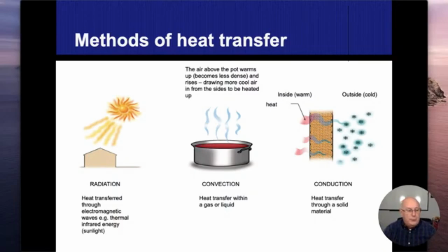Convection: anytime we move heat through water or air, we're going to be calling it convection. So in furnaces, we have ductwork. We heat up the heat exchanger, we blow our circulation air around the heat exchanger, and we absorb that heat. The fan blows it through the ductwork into the rooms where we want that heat. That's moved through convection. Hydronic heating systems use water. We heat up the water, we pump the water to another radiator, another location. We move the heat from point A to point B through water, hence convection.